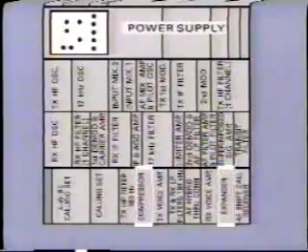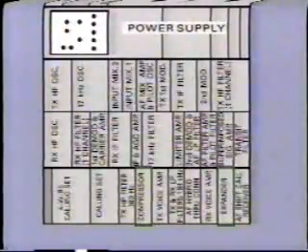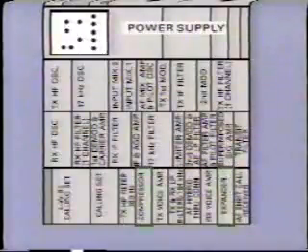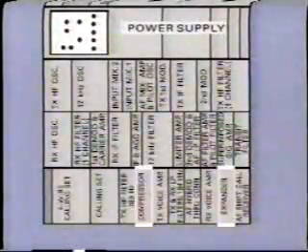Another special module or pair of modules is the compressor expander. The objective is to improve the clarity of voice communication. Much of the message transmitted by voice is in low-level sounds. The compressor compresses the dynamic range of the voice so that the weak sounds are transmitted at the same level as the loud ones. Then at the other end of the circuit, the expander does the reverse process so that the voice will sound normal. This technique also reduces the noise from line interference that is heard between syllables and words.